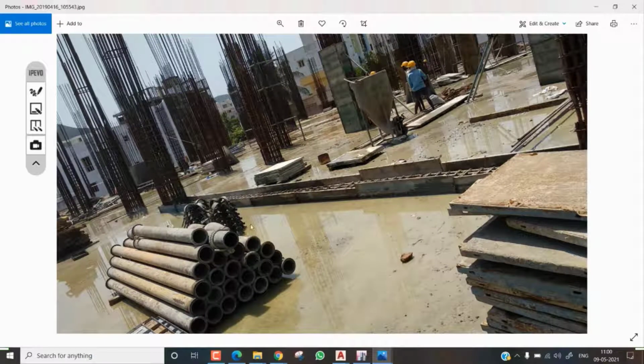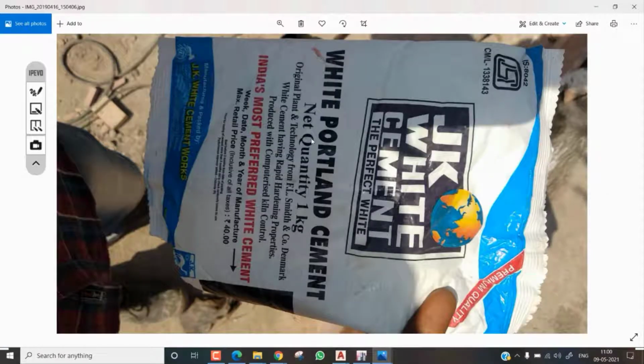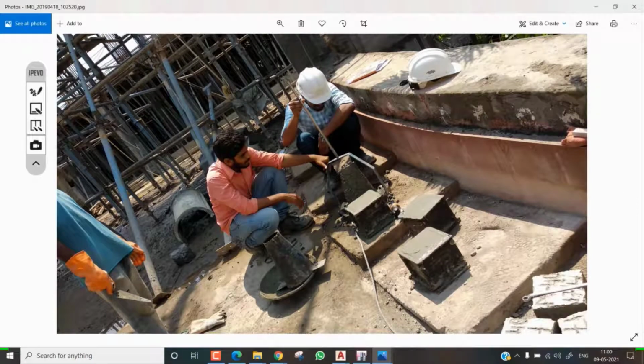These are the pipes we are using, and for the pipes when we are doing the concreting, and then this is some of the quick setting and micro cement concrete. When we will use the micro cement, I will tell you. This is a type of testing we will do. So once we have done the concrete, see this. The slump cone, we will cast these cubes. These cubes, and this is concrete equipment, and here is the flow of this, and we will check the slump cone.